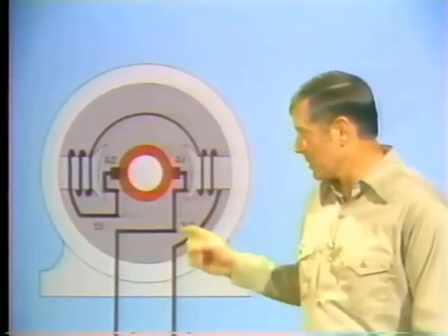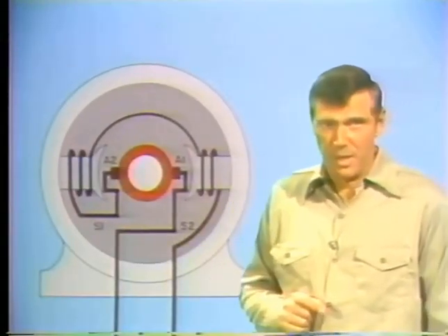There are several types of DC motors. Identifying the type you're working with isn't hard if you know what to look for, and you do need to know. Otherwise, you'll waste a lot of time. And you stand a good chance of damaging the equipment if you start looking for a problem before identifying what type of DC motor you've got on the bench. The methods used to troubleshoot a DC motor or to test it depend on what type it is.